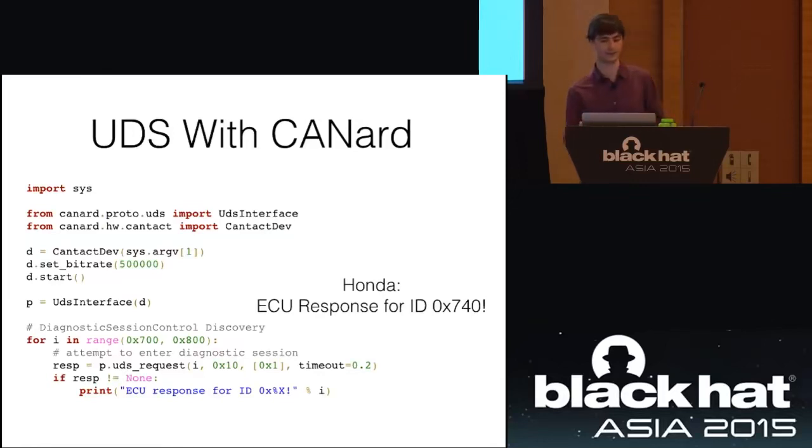What some people have done is that with the OBD2 port, they've kind of not air-gapped it, but they put a controller immediately after it and made it so you can only talk to that controller. The reason is mostly because when people start putting weird devices on their CAN bus, things like these insurance dongles that Progressive will give you in the States, or Desjardins in Canada, or even little data loggers made by who knows what company, that might have some issues.